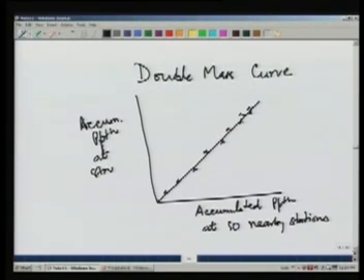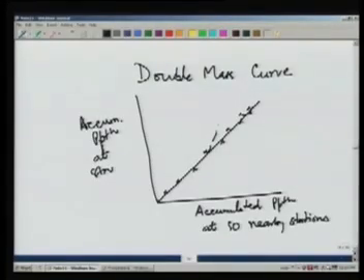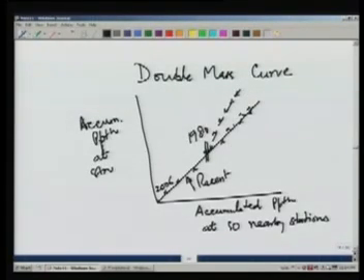But if there is some change in the characteristics of the catchment or the gauge has been shifted, there is some inconsistency, then we would see that the data does not follow a single straight line and it may deviate from that position. So if we plot the most recent data here, and then if there is a break somewhere, let's say we are starting from 2006, and then we find that in 1980 there was a break in the curve. So it will tell us that the data is not consistent and there is some problem.